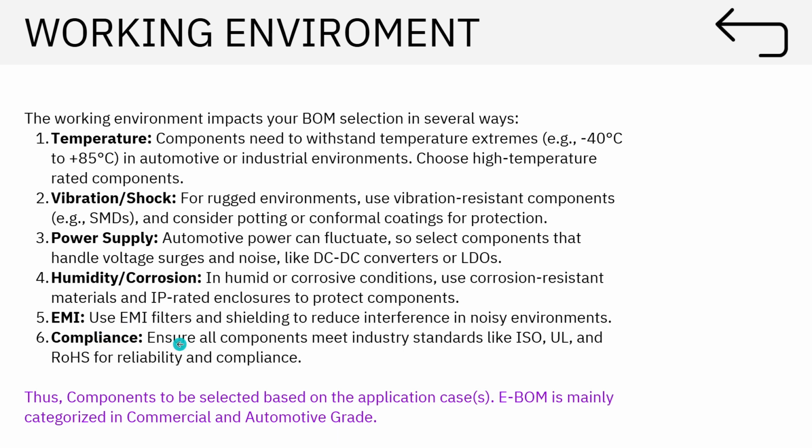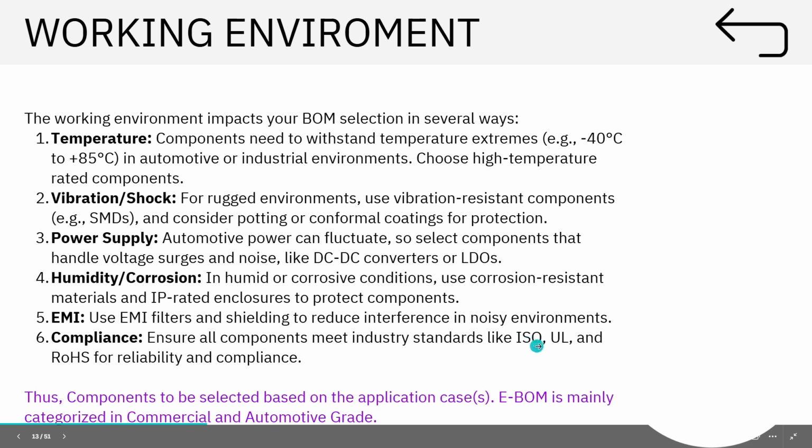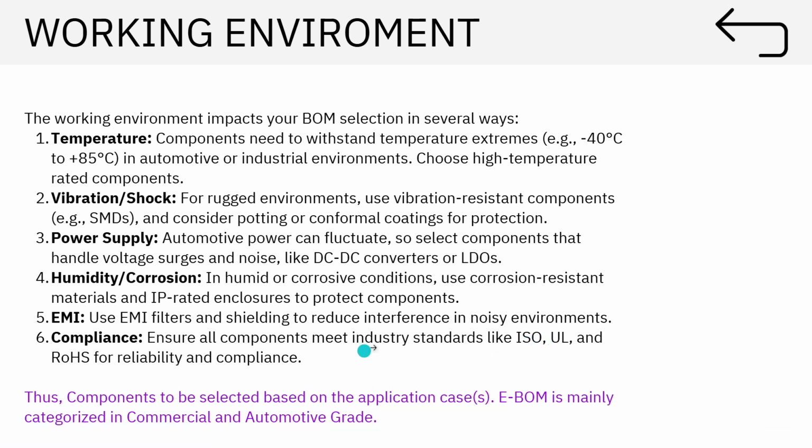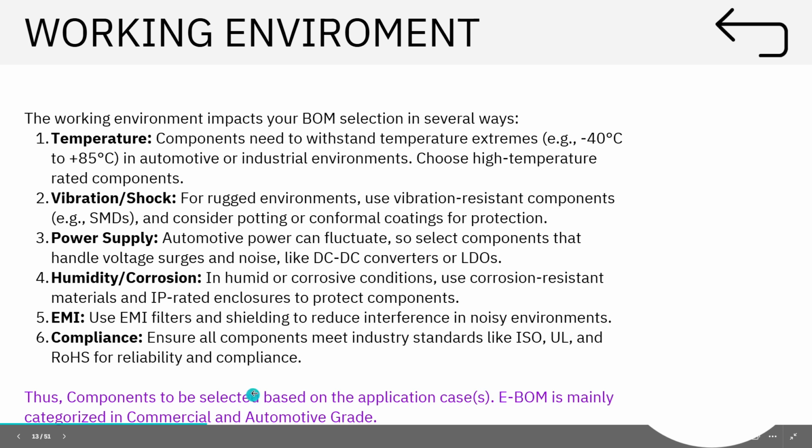Then sometimes you need to have some certifications. Since here there is no certification requirement because we are doing this internally, but sometimes you will have ISO or UL or RoHS compliance, reliability things to be done. So they are based on the standard requirement. You have to go read and understand what sort of isolation, EMI filtering and other things is required. So this working environment basically helps in selecting the BOM. And the BOM is mainly characterized as an industrial or commercial BOM, or the automotive grade.